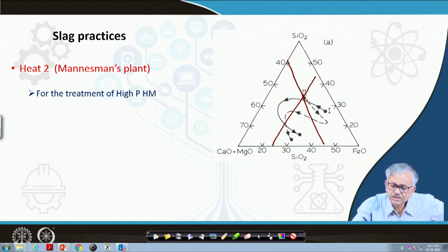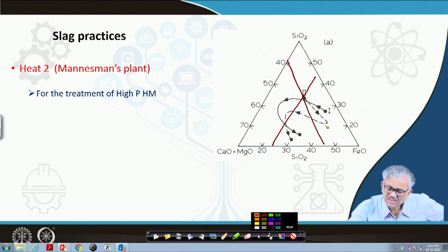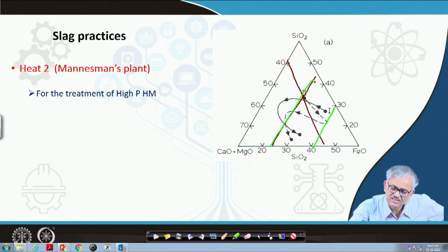So, again, what is going on there is that you are moving in this direction. Let me use some other line for iron oxide. Yes, it is coming. This is the iron oxide line. FeO was 20, and here you can find the FeO is very high because we have done a significant soft blow.